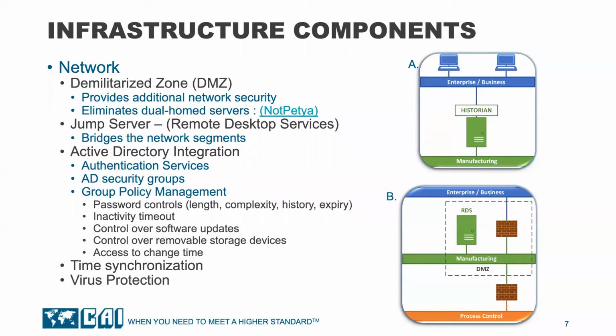Active Directory integration is important. It allows the security controls of multiple computers to be managed as a single group. It also allows one common service, Windows Active Directory, to provide authentication for all the computerized systems at level 3 and below. When Windows Active Directory authentication is used, users only have to remember a single password, their Windows password.